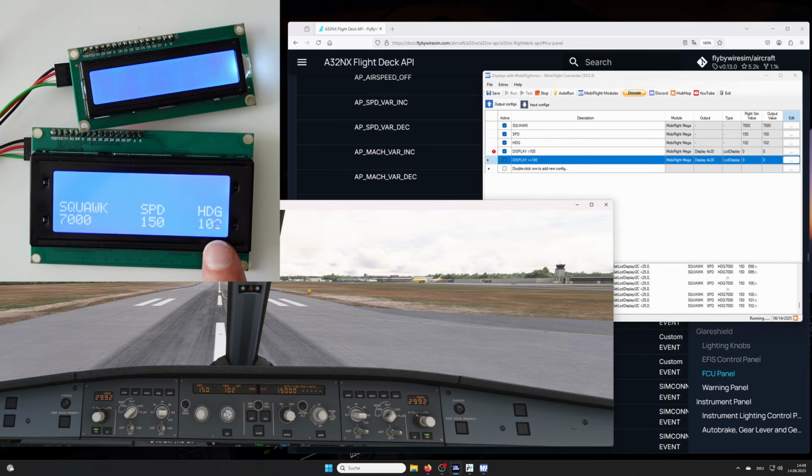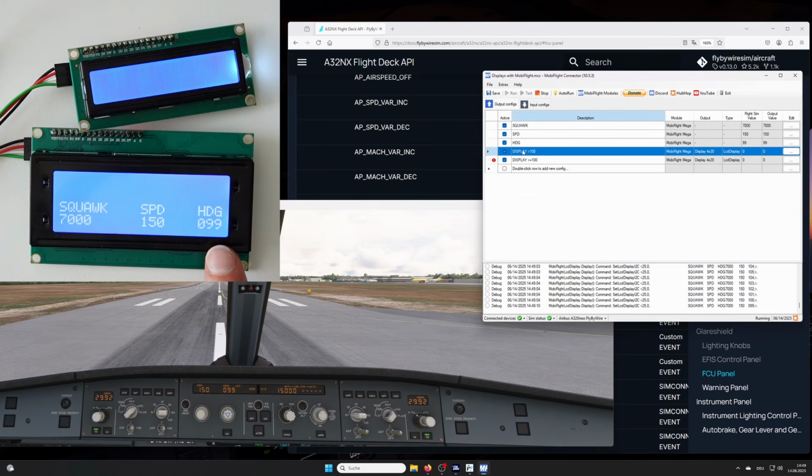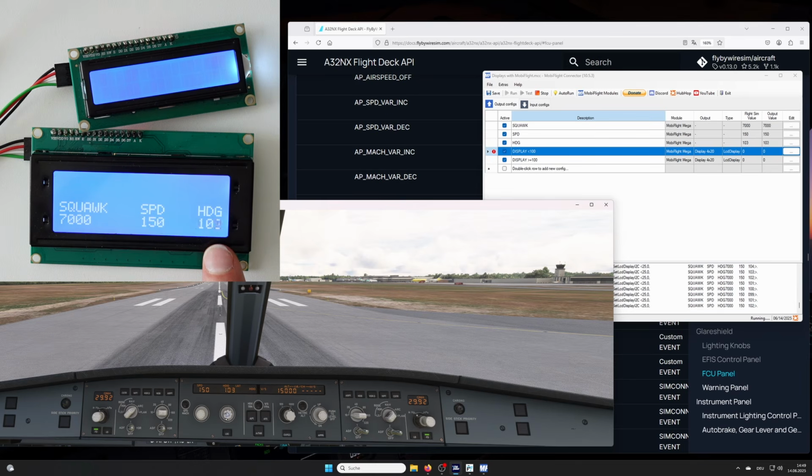I'm going to turn up the knob and have a look at the exclamation mark over here. When it's lower than 100, it switches. Now the precondition of the second row isn't there anymore, but it is with the display lower than 100, and now this configuration is executed. So when you turn the knob, you can see the exclamation mark is changing between the both configurations.